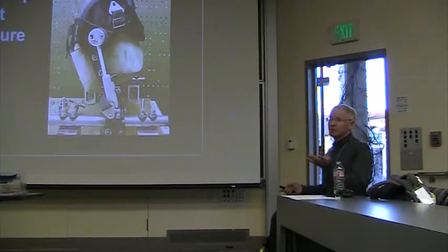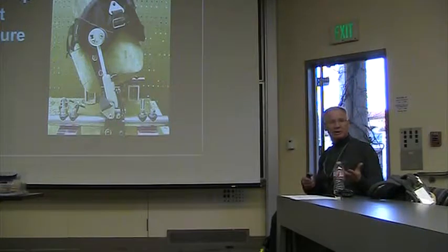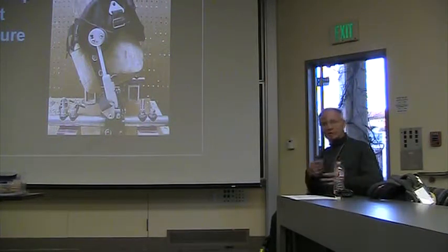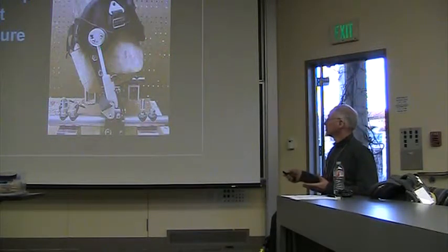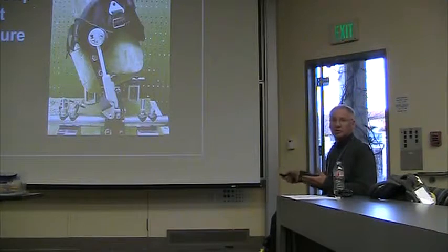And of course, we always test things. So whatever it is you're doing, think of how you can simulate using it a million times or whatever usage it's going to see. So in this case, we hooked it up to a motor with this rod right here, and the motor goes round and round, and the rod just makes it go back and forth. Test this thing a million cycles back and forth to make sure it's not going to fail.